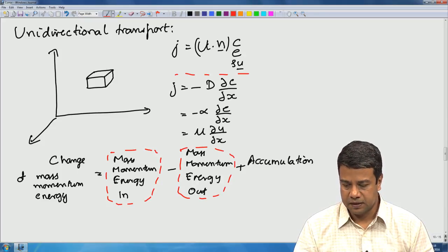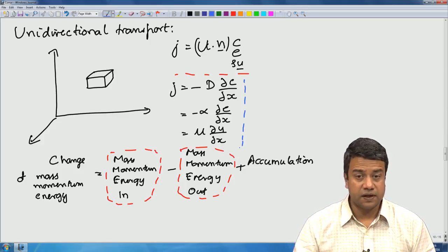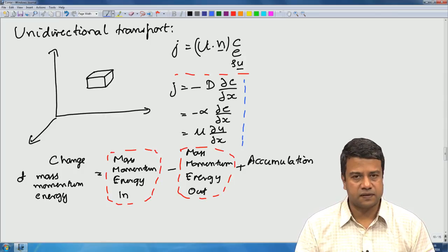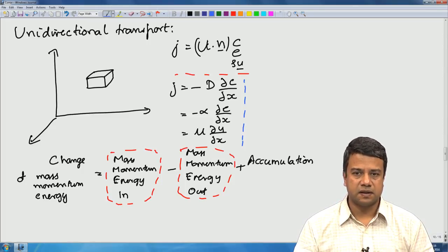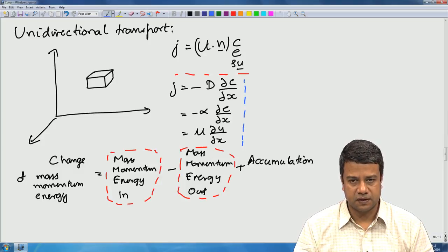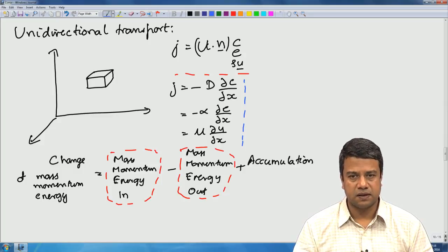Okay. The diffusion flux, on the other hand, is related to the variation of the concentration, energy, or momentum across a surface, and these are given by constitutive relations. They contain a diffusion coefficient with dimensions of length square per time times the gradient of the density of that quantity, the spatial variation, the difference in concentration divided by the distance.